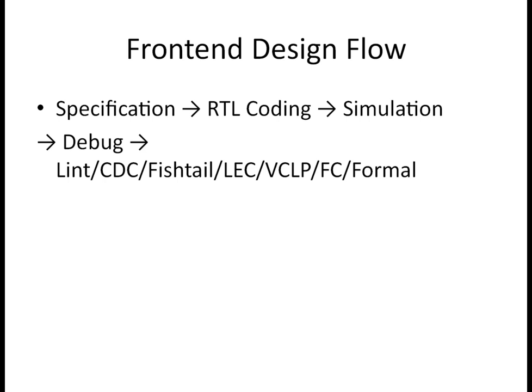Synthesis comes from Fusion Compiler, a tool from the company Synopsys. We can use Fusion Compiler to make sure our RTL is synthesizable, which means the RTL is converted to a gate level netlist. And there is one more tool called Formal, for formal verification, where we'll be checking the RTL.